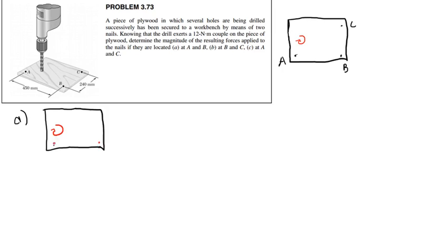Now, let us think about this. I have 2 forces and only 2 forces here. I have a force at A and a force at B. However, these forces have to be equal and opposite. They simply have to be. The reason they have to be equal and opposite is because this is not introducing any translational force. So if I had forces like this, just non-equal and opposite, arbitrary forces like this, there would be a net translational force on this object, yes?